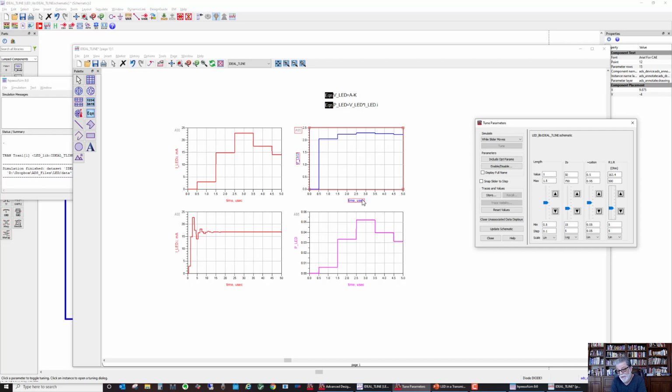Now, we do have to define lights because you will actually get lights from the LED at this 5 milliamps that occurs here in a half a microsecond, and of course it'll be brighter at 35 milliamps and even brighter at 50 milliamps. So the intensity of the lamp is going to change with time, up until we get to around 20 microseconds or so, maybe even 15 microseconds we can call it, which is a little more than 10 line lengths.